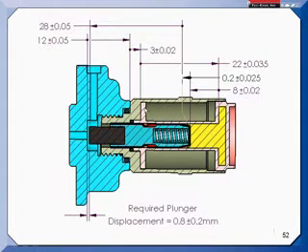When we look at the bobbin, it is coming up against this surface, and this diameter and that diameter are locating it. So the question to ask there is, who's going to win in the assembly? Well, when you look at the fit that I have on this diameter and this diameter, they're a pretty nice fit to this part, to the brown part here.